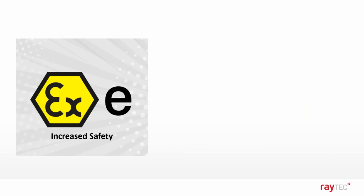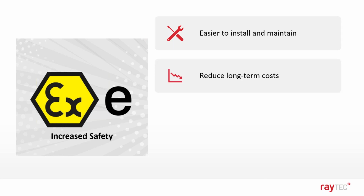So I know that we've covered a lot in those few slides. So let me just summarize some of the main points and benefits of an EXE luminaire. Firstly, easier to install and maintain due to reduction in weight and removal of flame paths, which means you reduce the long-term costs as a result.